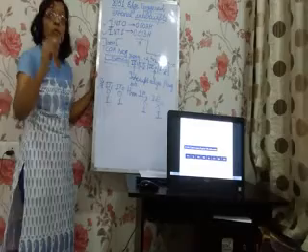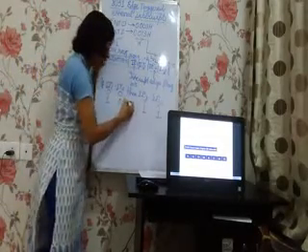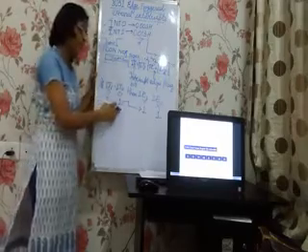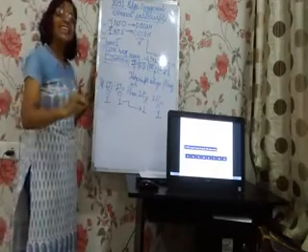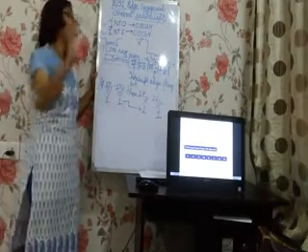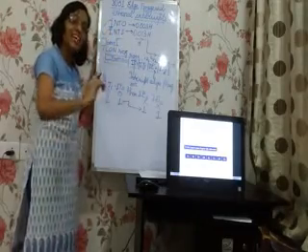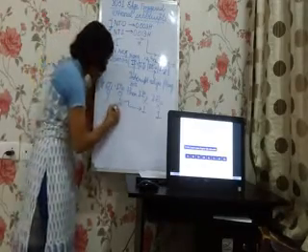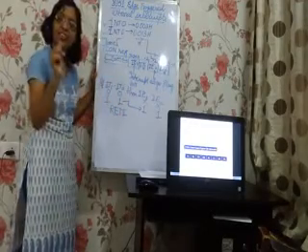When the ISR execution is going on, IE1 IE0 will be 1-1 if IT1 IT0 is 1-1. This will remain 1 till the interrupt service routine is completely executed for INT0 and INT1. Once the ISR execution is over, what is the last instruction of ISR? It is RETI, return from interrupt.